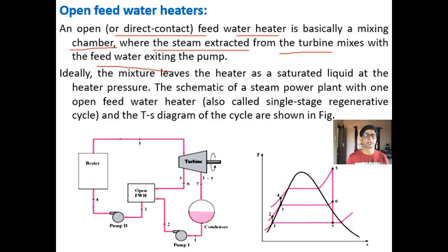So this is feed water. You can see here, from the boiler, steam enters the turbine. Actually this point is a mistake in the diagram. You should draw it somewhere here. So it is extracted at some point here, not here. Change this point, because at the same point you cannot extract the steam. After a bit of expansion, steam is extracted. What is the quantity of steam extracted? So y, right?